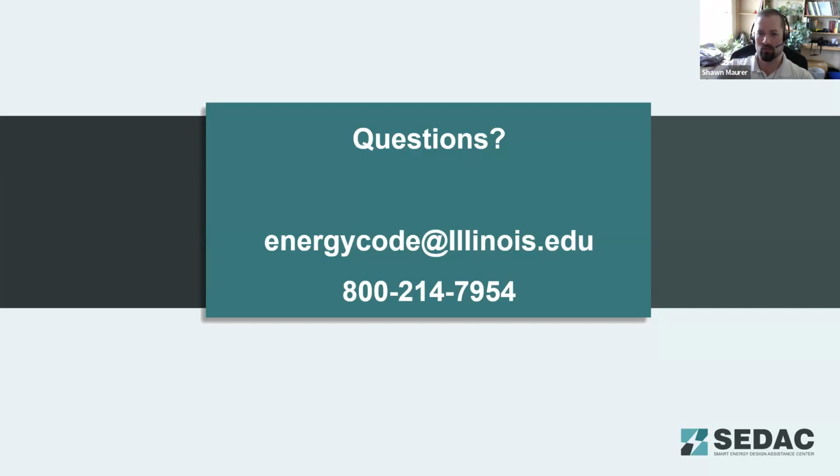So we had a poll question earlier. It was a garage that had a new system that was heated and cooled. That new HVAC system is not exempt from duct testing requirements because it's a whole new system in that garage. So a little bit of a clarifying question there in the Q&A for that poll question in the additions section of this presentation. So it was a heated and cooled garage. It's exempt from the air leakage testing requirements. It has an HVAC system installed that does not allow it to qualify as a low energy building. So it's using too much energy in BTUs per square foot to qualify for that. So it has to meet the full insulation requirements. Since it's a new HVAC system and not an extension of the existing duct system, the duct system has to fully comply with the insulation requirements.